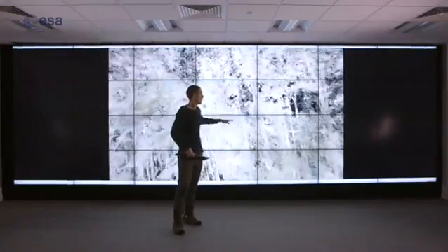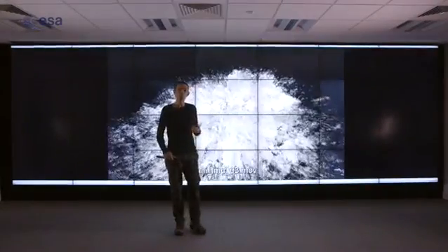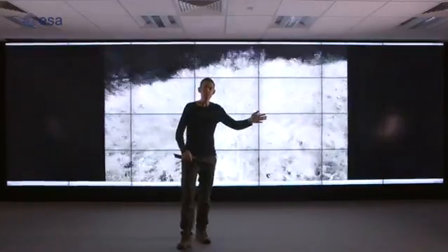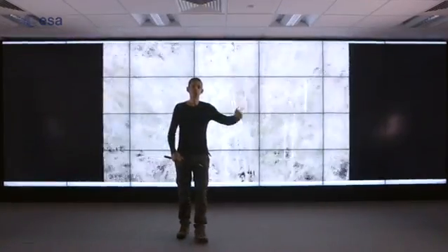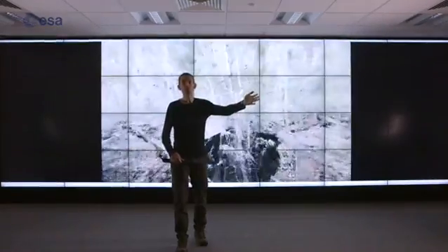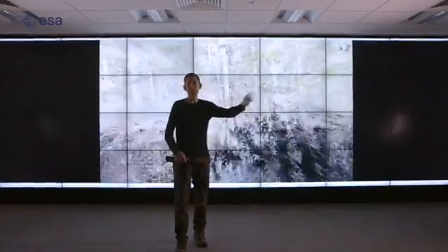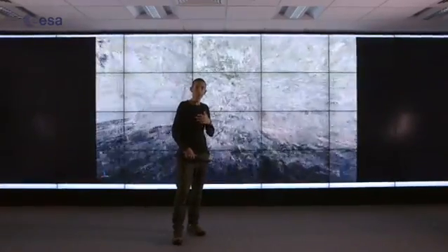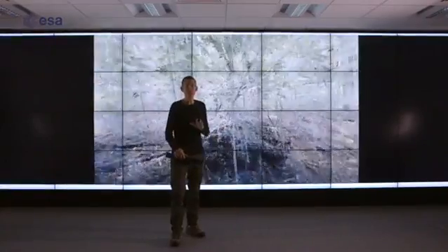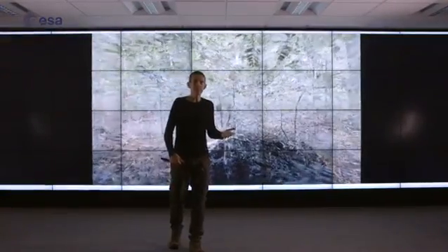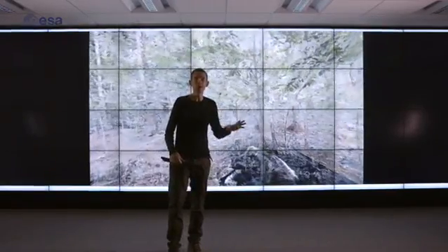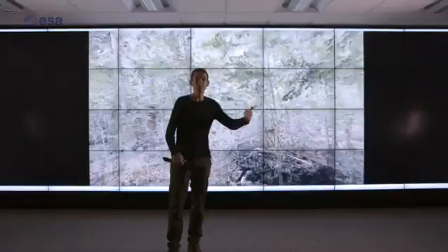So these particular measurements were made using a terrestrial laser scanner, or LiDAR scanner. LiDAR is a technology that fires out laser beams and essentially measures the distance that laser beam reaches before it hits something, and then the energy is returned back to the sensor. So LiDAR is a kind of technology that's been widely used for a range of different applications. It is in essence a remote sensing measurement. It's been widely used in the past for things like surveying applications, for measuring distance very accurately.